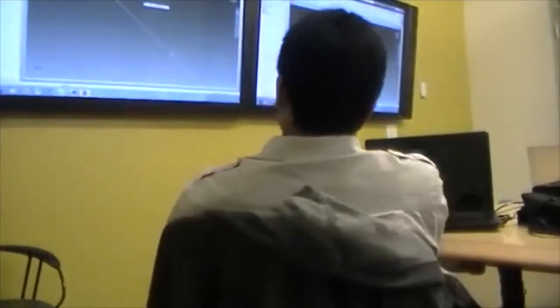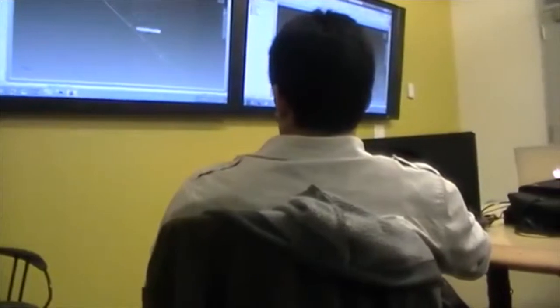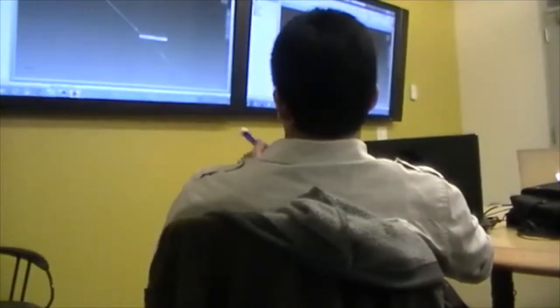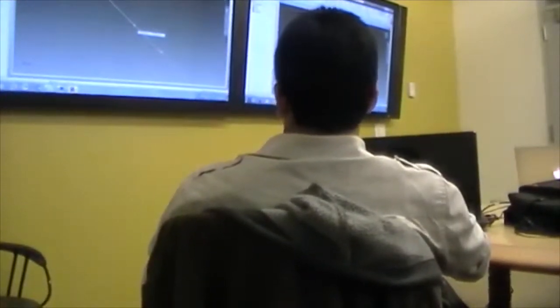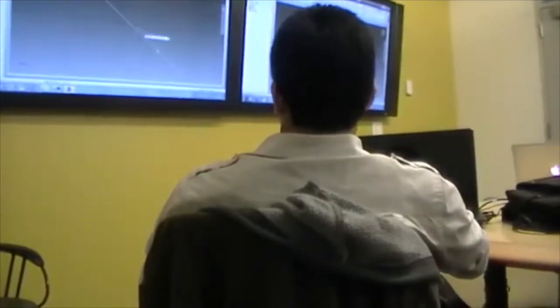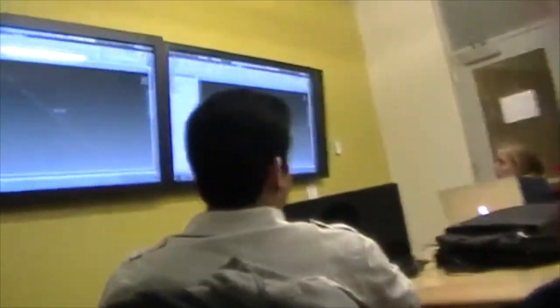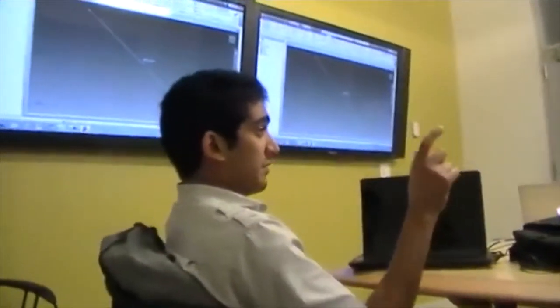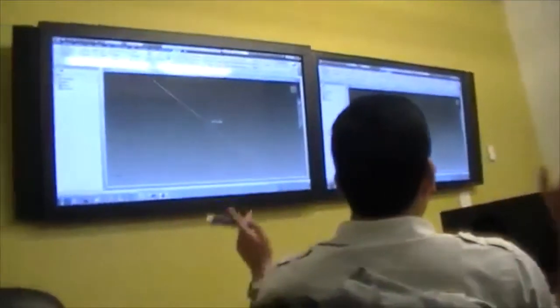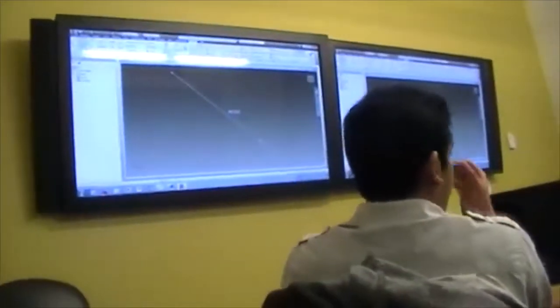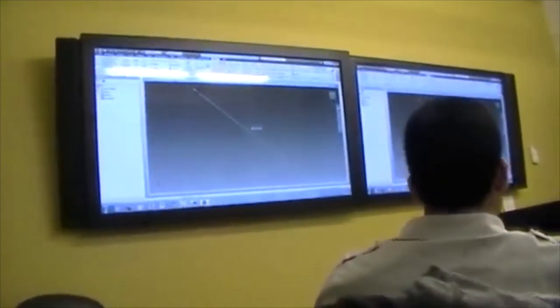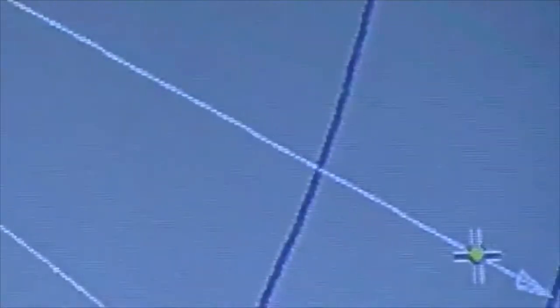Okay. So there's a couple of different ways to do this. Remember that we want the center part to be hollow. So what you can do is either A, draw another circle that's either concentric or kind of outside of this. Now, if we want the inner diameter to be 50 millimeters, you want to set this on the outside of the circle that you just drew. So let's say we want a 10 millimeter thickness, I set that to 60. So that's one way to do it.